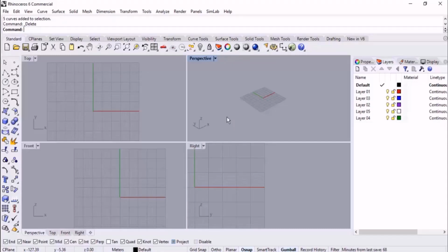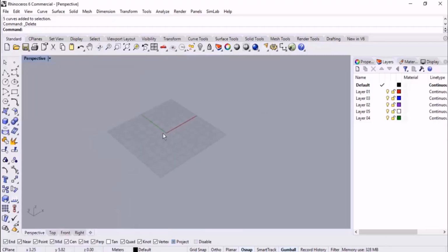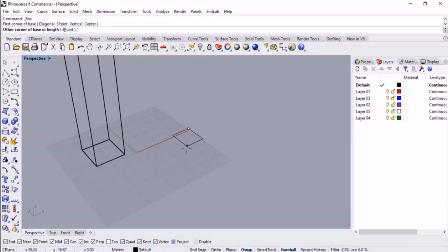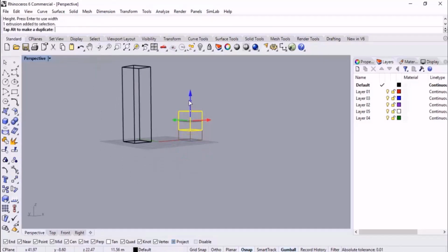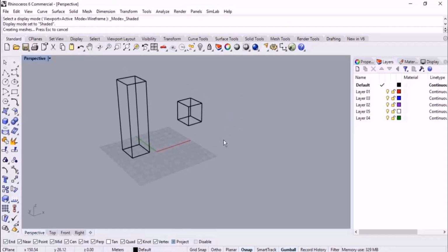Following that, I'm gonna tell you another application for planar and project, and then I give you time for practicing. While you are using move, copy, and array tools in the 2D views, you have to enable project and planar, so it moves the objects or the curves correctly and avoids the unwanted movements. In this example, I will tell you, for example, by using the move command. Suppose that here we got a cube like this, and then another cube there. Let me move it a little bit. For example, I place it at the center.